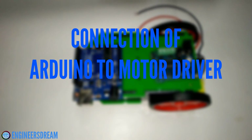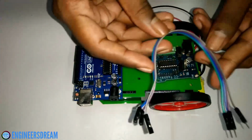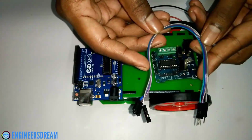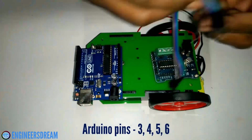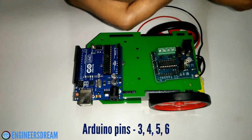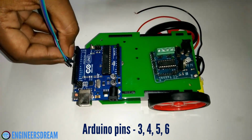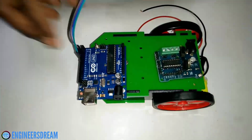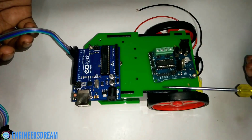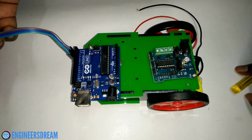So after understanding the working of the motor driver, it is now time to connect the Arduino to the motor driver. First, I'll take 4 male to female wires for connection of the motor driver to the Arduino. Now, for programming the robot, I'll be using pin number 3, 4, 5 and 6 from the Arduino. So I'll attach the male part of the wires to Arduino's pin number 3, 4, 5 and 6. Next, I will attach the other end of the wires to the input pins of the motor driver, that is D1, D2, D3 and D4.